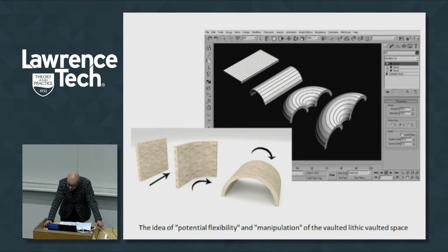It's interesting to note that the term arch, from the Latin arcus, contains the idea of bending, from the Latin plicare, in a topological sense. Arcus and plicare, bend, is inside the word arcus. The idea starts from a very simple consideration, that is the observation that most vaulted systems can be imagined as a discontinuous structure like a masonry wall that can be folded or deformed in order to obtain its final geometrical structural shape. For example, a stone wall can theoretically be bent to become a barrel vault, or by going on to be bent it becomes an annular one, and thus a helicoidal barrel vault.